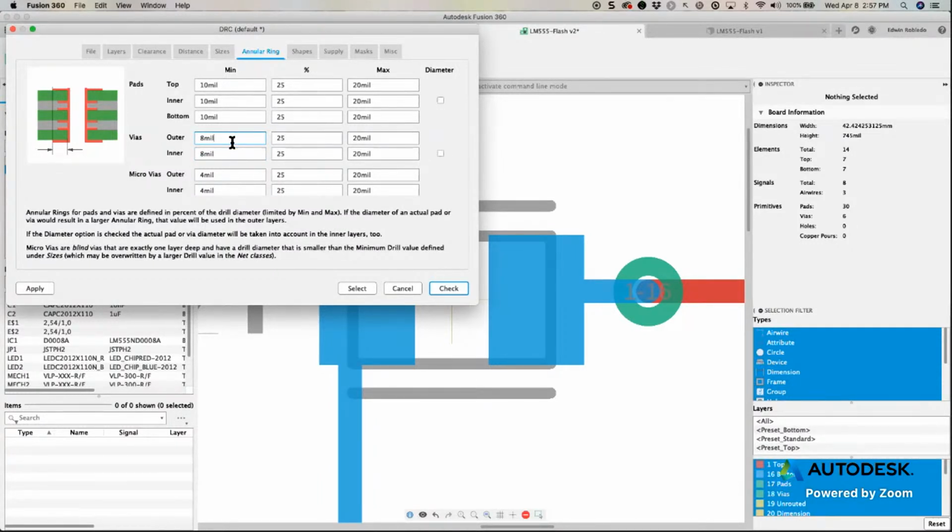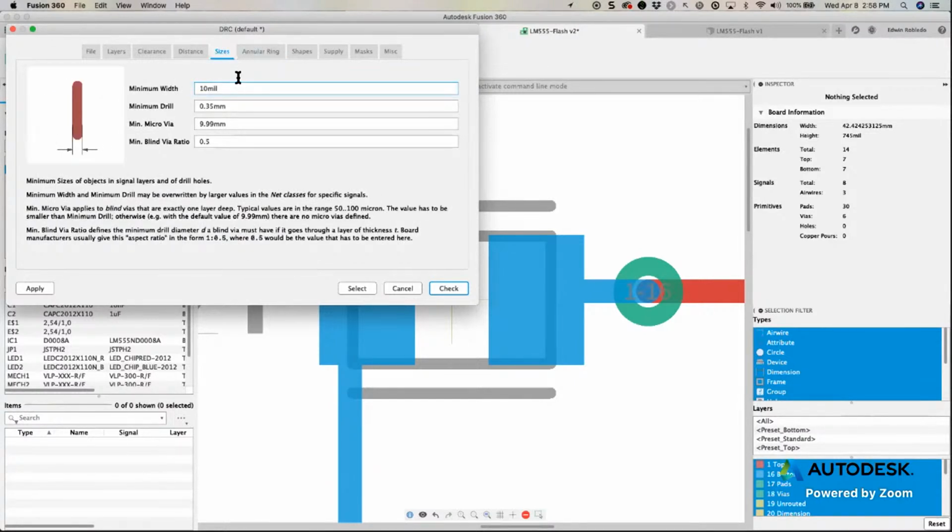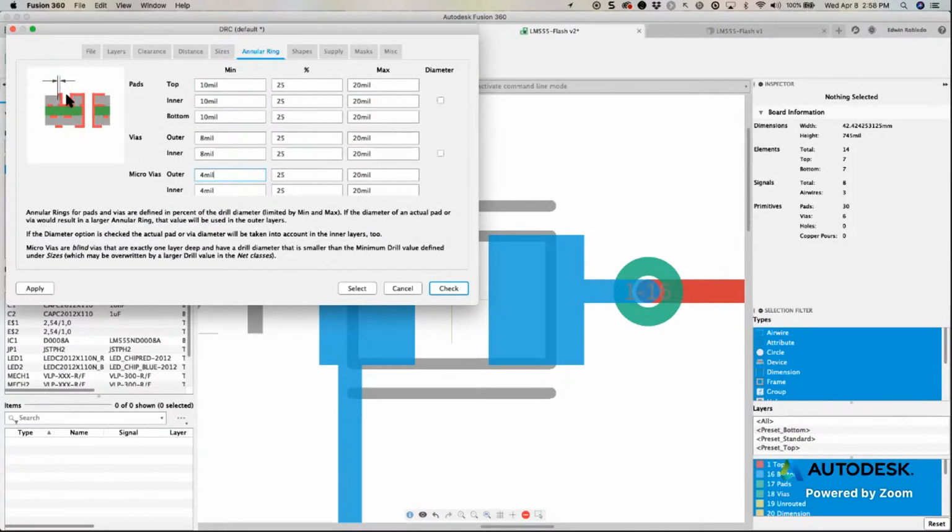It's just the right size that it uses. So you only can control the top as well as the bottom. And as we said earlier on our microvias, if you're going to be using microvias, it's just the size that is going to be used right there in this parameter that you see right here. Remember that we were talking about microvias right here? So that's just how big the plating is going to be for our microvias.